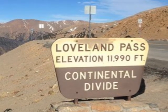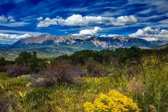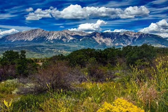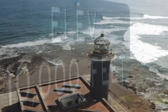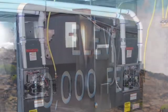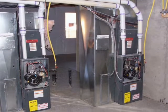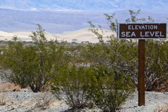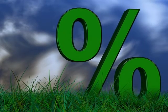Remember that Manual J is what lists the elevation of the project. So in Colorado, we're kind of high, meaning elevation-wise, yes? Mechanical equipment works better at sea level than it does at 10,000 feet. Absolutely. For gas-fired appliances, there will be a deration based on every 1,000 feet above sea level. Now this will vary amongst manufacturers, 2 to 4%, somewhere in there.